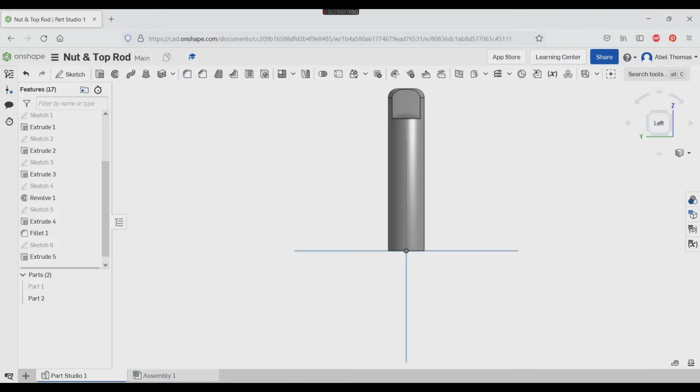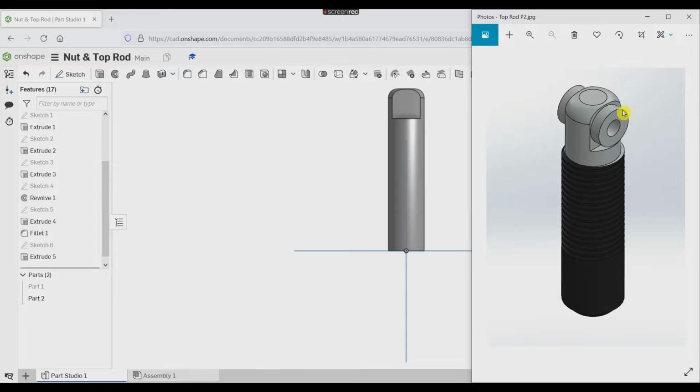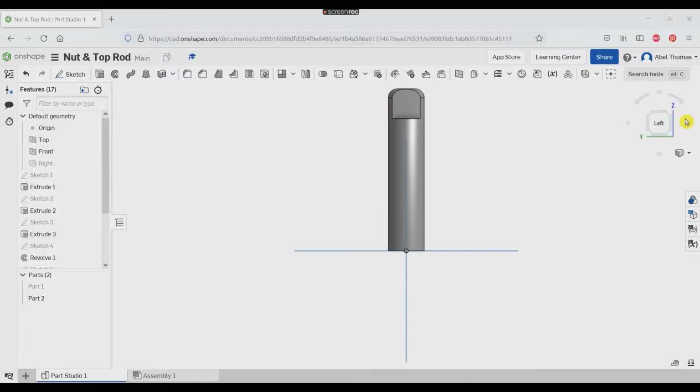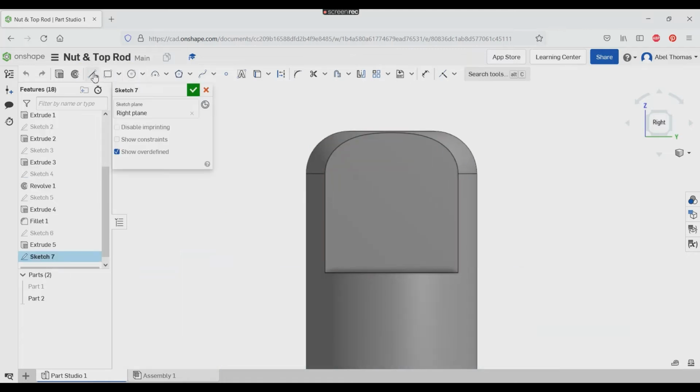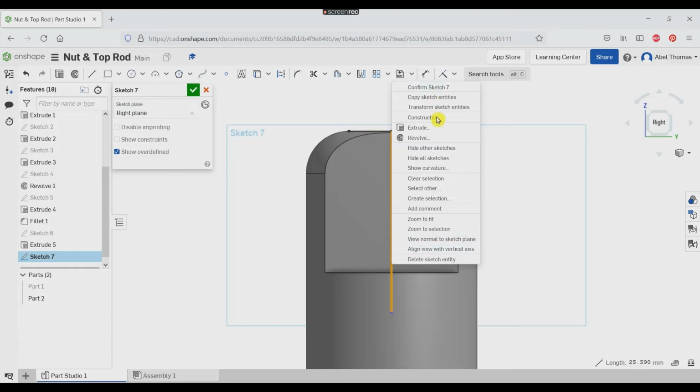So now we need to add this hole in here and also add this extrusion here. Let's create a hole by sketching on the right plane, just making this normal to us, and you could make this visible. Add a new sketch. Okay, first we need an axis right about here, but since we can't use this end line, we have to click on use to use this line. Okay, so that has been done. We'll add a new line from the midpoint here down here. Okay, click escape, set this to construction line.